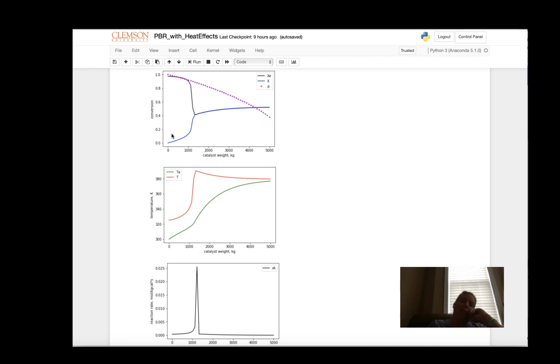So this is actually a pretty significant issue in reactor design and also catalysis. A goal of catalysis would be to define a catalyst that has a lower activation barrier, which means that we can get to a higher conversion sooner. In fact, this being a catalytic reactor already, that would mean we would want to find a more effective catalyst where we don't have this kinetic limitation, which is preventing us from achieving the equilibrium conversion, which at these temperatures is quite high.